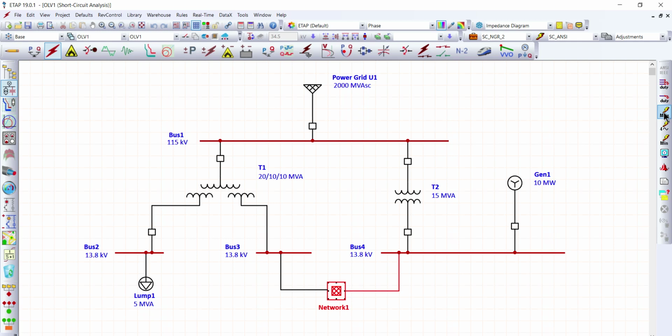Generator, motor and transformer grounding types and winding connections are taken into consideration when constructing system positive, negative, and zero sequence networks. Any adjustment for the impedance is taken as negative in order to produce smaller impedance, and this yields higher short circuit currents. Okay, next, this one, run 3-phase, line to ground, line to line to ground, 1.5 to 4 cycle.